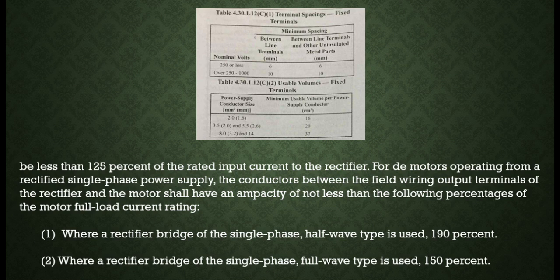For half-wave rectifier bridges, use 190% of the motor's full load current rating. And for full wave bridges, 150%.